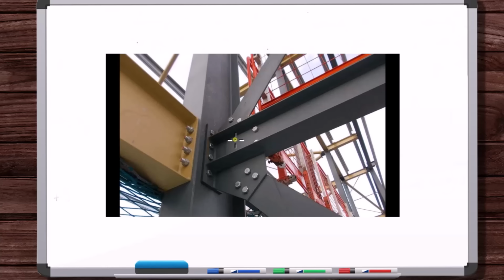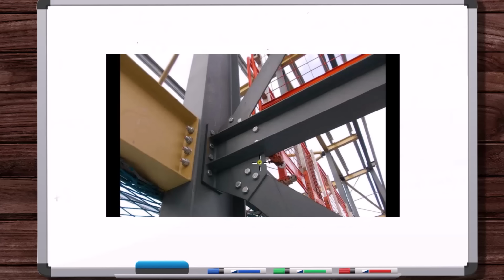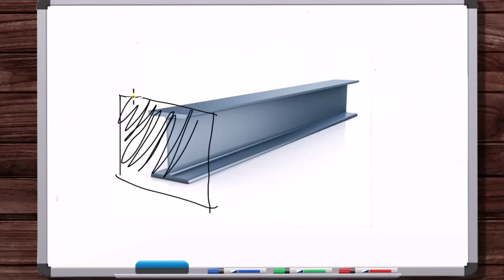Okay, but one thing I can also do, again, I could remove this beam here, move it into empty space by taking it off how it's connected to other pieces, or I could make a cut in the beam, an imaginary cut, a plane. Right, so if we come here, imagine this is the bolted end. So this is fixed. That's this end of this beam. And let's just say, hypothetically, we unbolted the other end. So this is a free end. And let's imagine there's a load here.